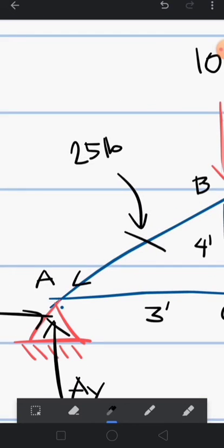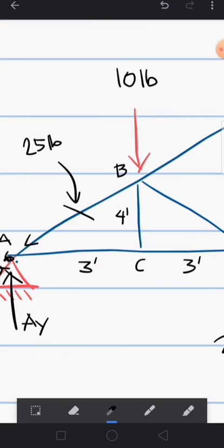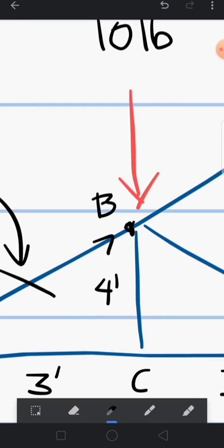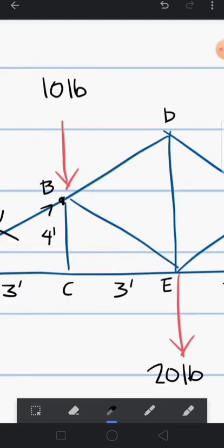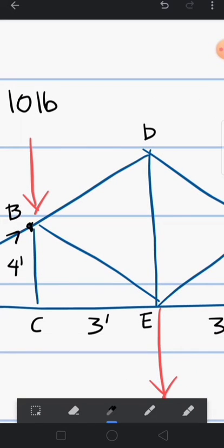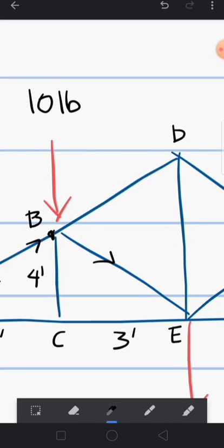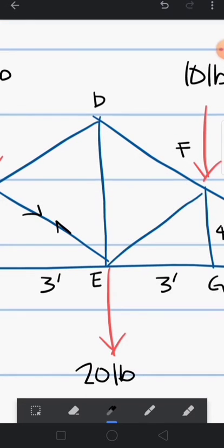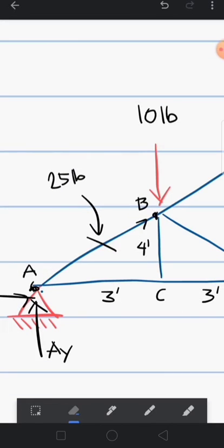It is in compression. And if this AB compresses joint A, then at B it also compresses B. And if, for example, BE here stretches, it is in tension, and of course at E it is also in tension. That's all, so you don't get confused with the signs.